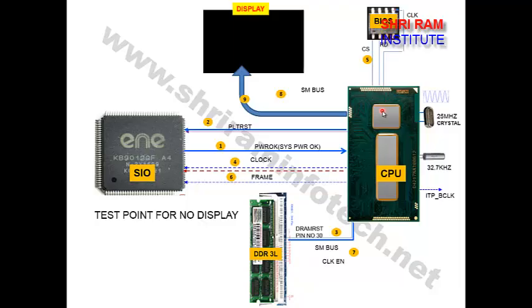In all circumstances, first you have to heat the motherboard with this OTG oven. Put it in the oven or try to heat on the BGA machine at 220 degrees. If after the heating the problem is still there, and the CPU doesn't send this chip select signal, then the possible fault could be the CPU.